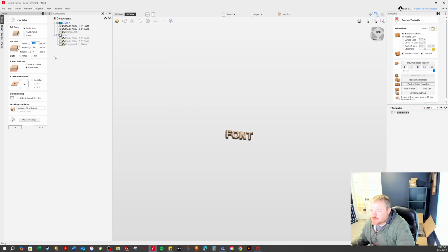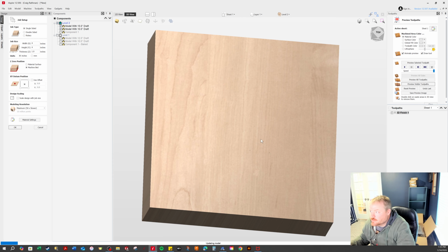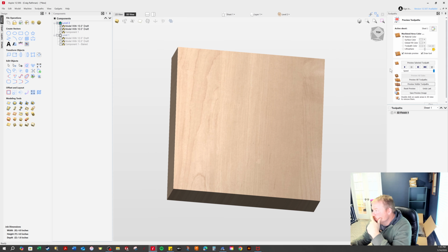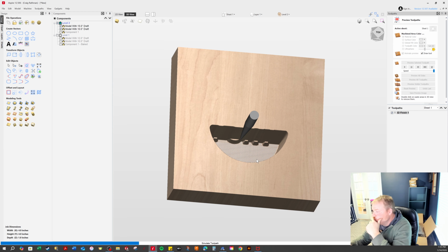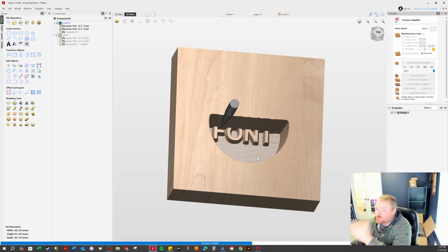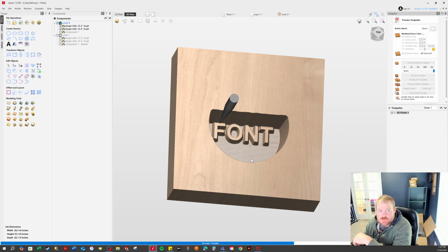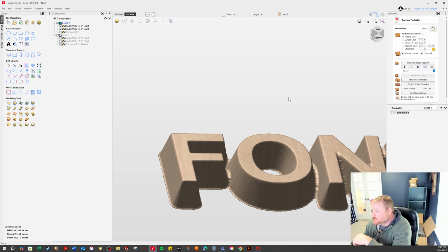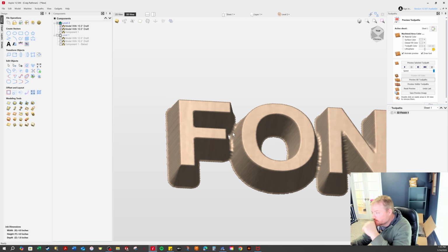But also, depending on how big your job size is, it's going to affect how pixelated your stuff is. So if we go down to 4x4, it should look a lot better and give you a better machine preview. It's also going to take longer for it to run through the preview. See, yeah, it gives you a lot better idea of what it's going to look like.